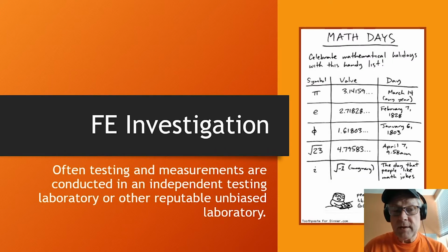In investigations I'm involved with, I usually develop a matrix of testing protocol, test procedures, and test methods to follow, whether they're national standards or local standards or regional standards that you're working with, and ultimately to be able to obtain additional information from an unbiased laboratory, a laboratory that has had no role in the project. Typically an AASHTO accredited laboratory will be engaged when I'm doing forensic work, and other forensic engineers, I'm certain they do the same thing. Really no reason to include people who have been involved in the project at this point.